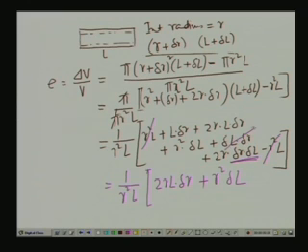Now, this quantity we also neglect, this is L delta R square. So, this term also we neglect, delta R being small, the square of that will be very small, and also delta R delta L being small, the product of delta R and delta L we also neglect. So, we are left with these two terms, and if we divide by R square L, this becomes twice delta R by R plus delta L over L.